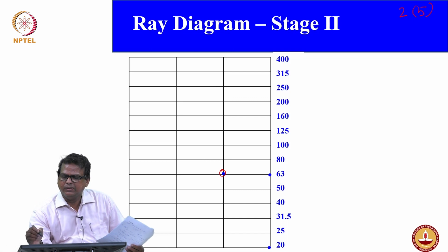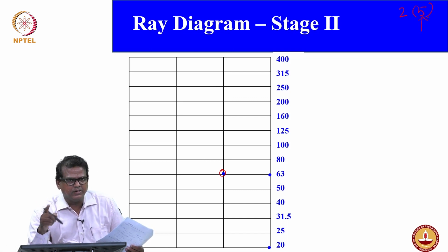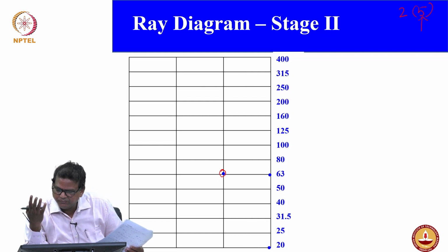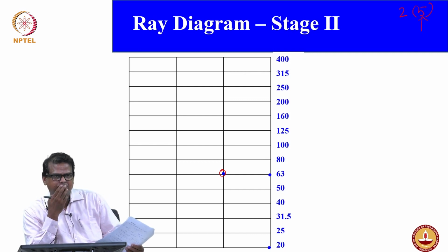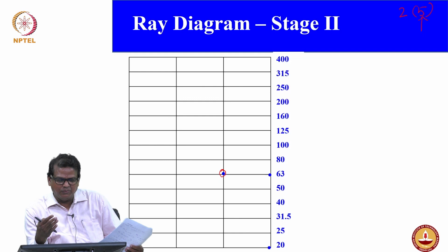See, these are the input speeds, right? Each input speed will give you 2 output speeds. That we got. So where are the other input speeds? That's my question. We need to have another 4 input speeds, right? So how are we going to do that? What are the possible input speeds of stage 3?